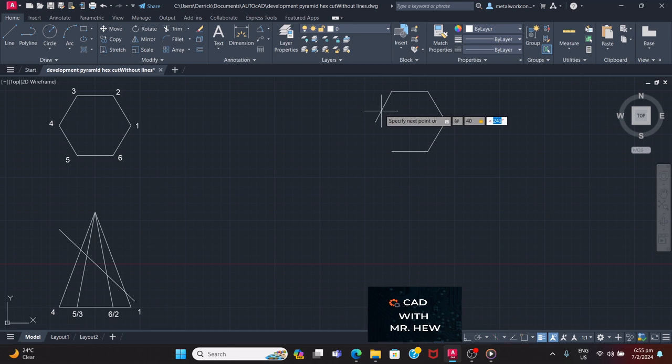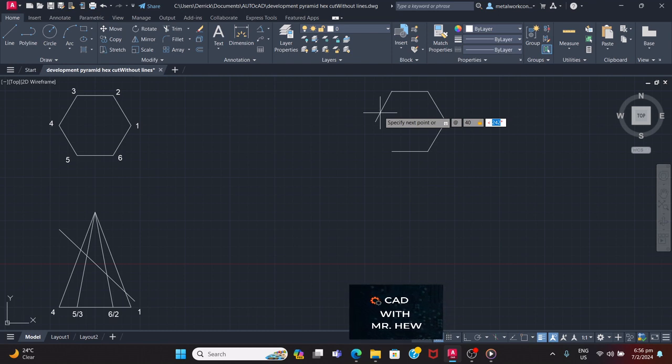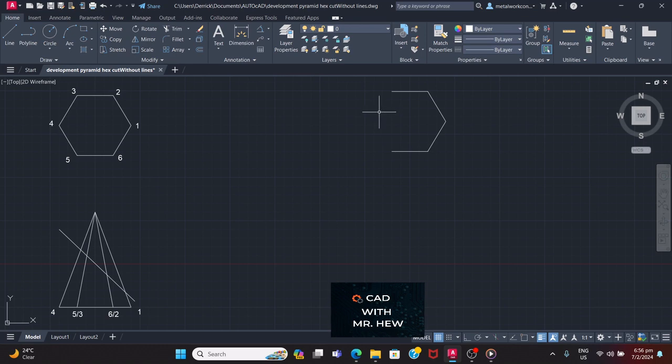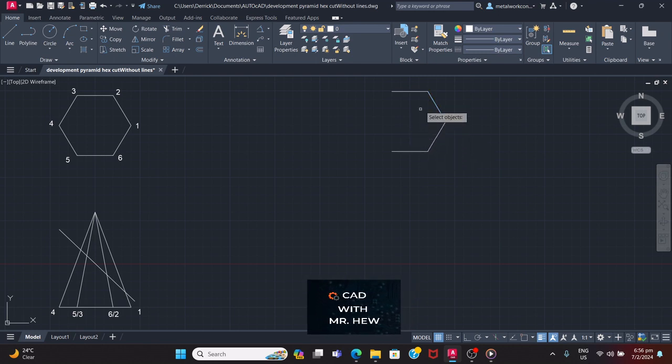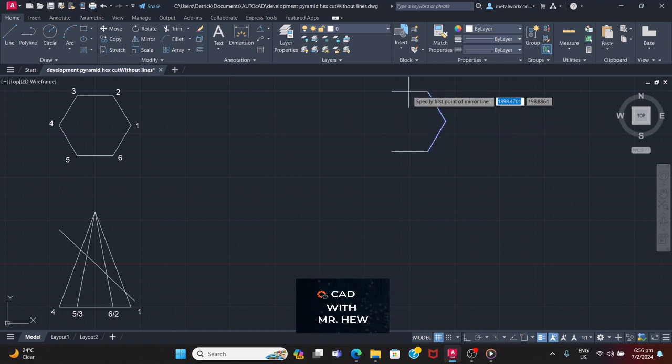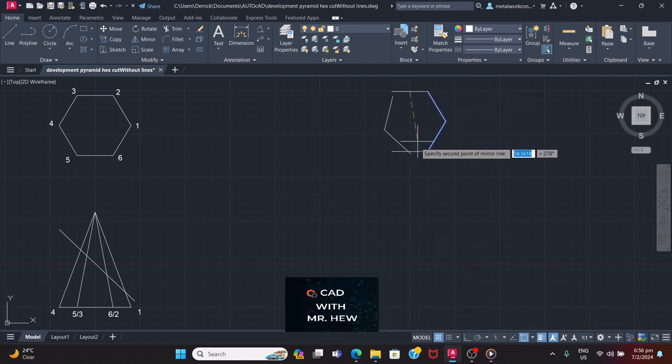All right. So what we're going to do now, we're going to draw the sides to the apex. Let me label the top here, the apex. All right, that is the apex. We're going to draw lines from the apex to the corner, which was projected from the plan. Good. So we have our basic pyramid, and what we want to do now, we're going to get the cut.